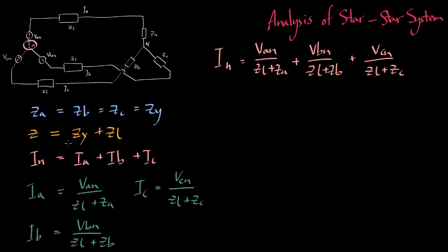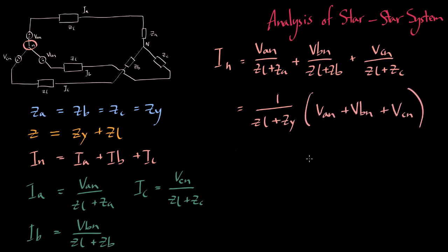Knowing the generalized impedance per phase, we can further rearrange this. Finally, we can readily infer that the line currents add up to 0. Thus, the current at the neutral point is equal to 0. It can be clearly seen how this applies to the other neutral as well. This means that in a balanced system, if the current in the neutral is 0, a neutral wire is unnecessary.